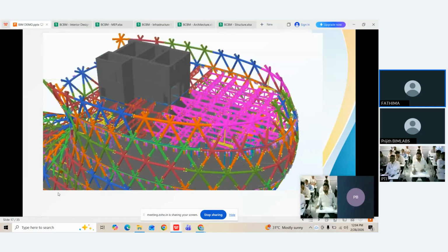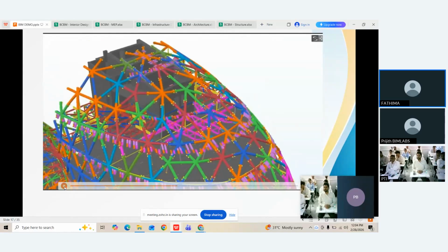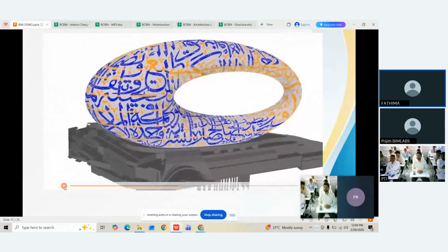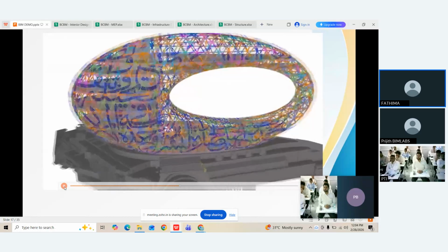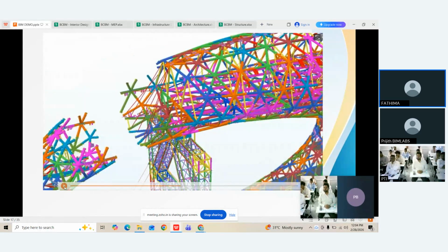The steel work took 14 months after the reinforced concrete ring beam and tower that support the diagrid. Laser scanning was utilized to compare the as-built placements to the 3D model. The detailed 3D modeling also eliminated normal MEP installation issues. MEP frequently stymies a project late in the building phase.